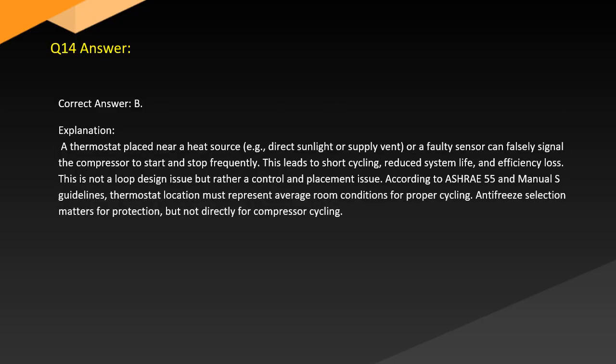Answer. Correct answer: B. Explanation. A thermostat placed near a heat source, e.g., direct sunlight or a supply vent, or a faulty sensor can falsely signal the compressor to start and stop frequently. This leads to short cycling, reduced system life, and efficiency loss.